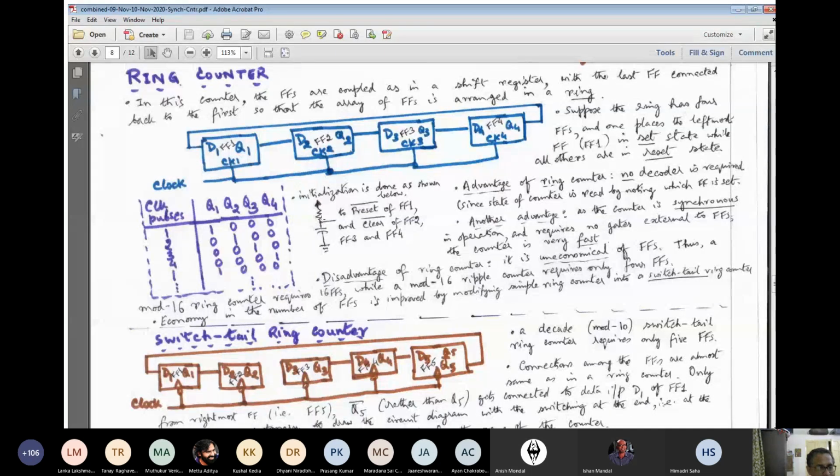Normally the asynchronous set and asynchronous clear inputs are active low. So the moment the capacitance becomes charged up, its control is no longer required. Only at the beginning of the operation of the circuit, it will be logic 0, and hence it will affect the asynchronous set and asynchronous reset of the other 3. So then the initial state will be 1 0 0 0, but after that it is normal operation. Is it clear now how to initialize the state of a counter?